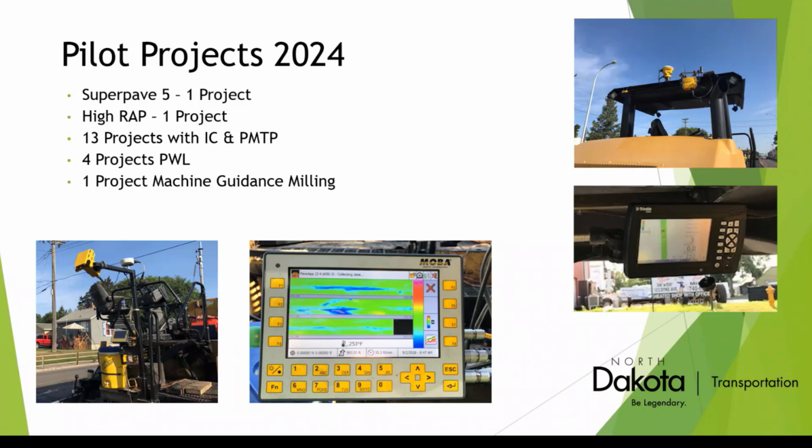Well, I need to slow the milling operation down to get the intended crown and slope control, but at the same time, I have to keep that 1.5 inch max wrap material under control. And the faster I go, well, if the milling company is a subcontractor, they want to get off that job and go to their next one, and they got 5 more to go after that. So there was always this constant tug of war going, and still is, on projects.